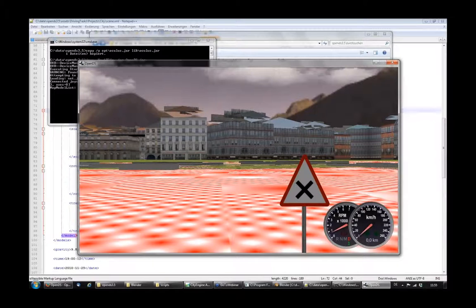Well, there are some issues still remaining, as you can see. For example, the texture in front of the car has red and white spots. So this obviously means the texture has not been found here. Especially in the use of CityEngine, this is a result of the naming of the texture files. So I show you how to solve the issues about the textures.